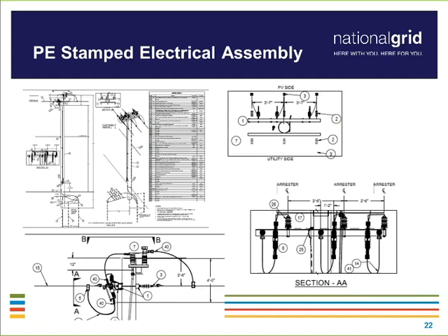When we receive a paper product, a two-dimensional drawing, in order for us to visualize it, we have to see things at different angles to make sure all the spatial arrangements are going to work with respect to our requirements, and make sure all the equipment is there per our requirements as well. And so, for instance, this one has the elevation view, and we have a top view, and then there are two different side views or section views, which properly give us enough information that it would be a satisfactory submission so we can approve it and move on to construction.